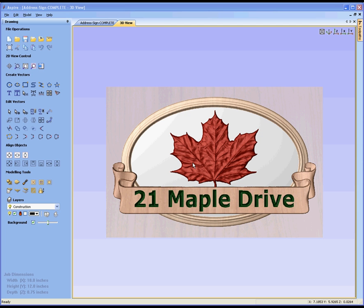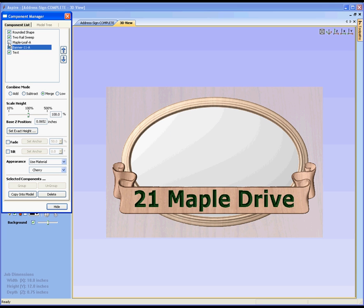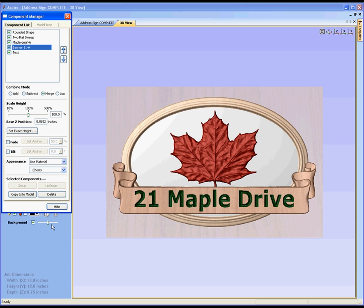In the 3D view, you'll encounter a number of different things. What we can see at the moment is basically the current visual components. If we pop up the component manager, then we can see that all the components are currently drawn. If I uncheck any of these, then they're going to be undrawn from the 3D view, and that also means they'll be excluded if we created a toolpath. So we'll just switch that back on.